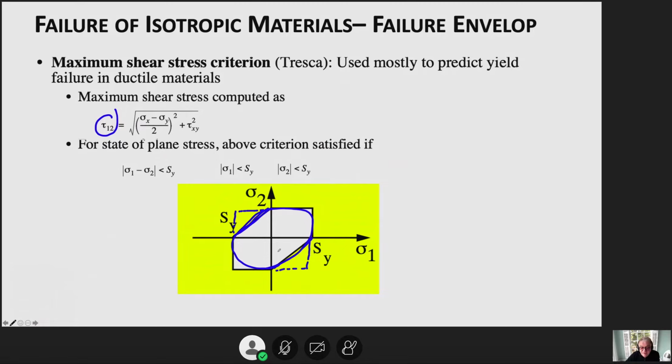any of the other criteria, because when we do the experiments for isotropic materials, with different combinations of sigma X and sigma Y, and then we compute the sigma 1s, taus and sigma 2s, you find that failures typically really do not go in here. They don't fail here. They failed before. So these will be like experimental data. And of course, occasionally there will be experimental data outside, but not necessarily coming here. So you hardly reach these points.